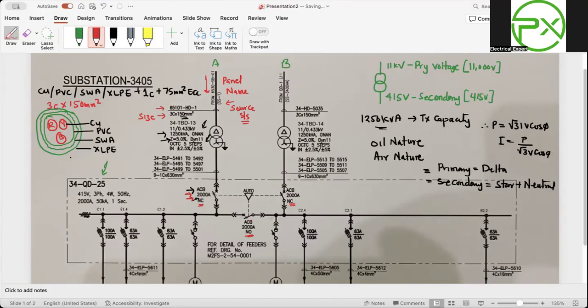Okay, so this breaker, especially this one in the bus coupler, connects both the bus sections. If the transformer fails, the system here, they normally call it sectionalizing, right? One of the main functions here is for load sharing, right?